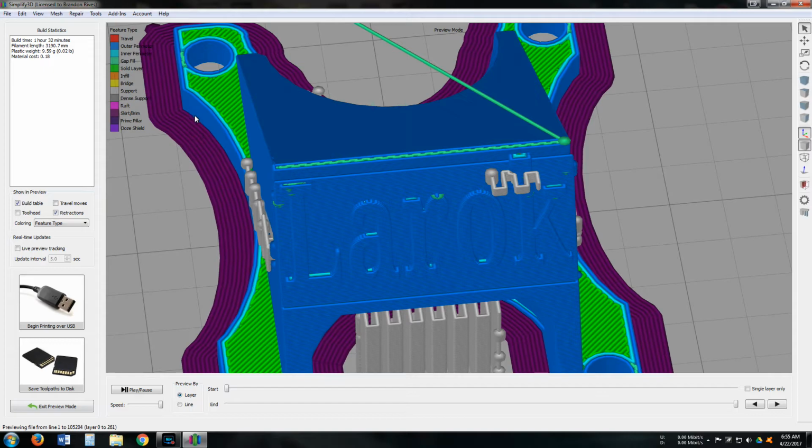The brim basically prints this, you see this purple part here? That is your brim, and it connects to the bottom 3 layers. Now, you can put how many layers you want. I just find that 3 layers is pretty good. 3 layers tall, and then we have 8 beads out. So 3 layers and then 8 beads out.